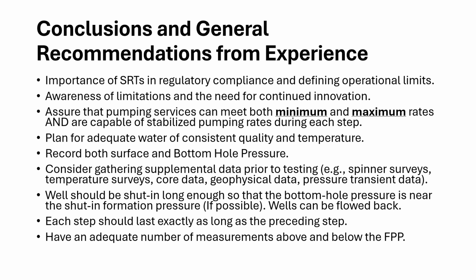So I would recommend that pumping services, when you're preparing for a test, be able to pump at the minimum and the maximum rates in your procedure. Oftentimes, the minimum rate is going to be a quarter barrel per minute or a half a barrel per minute, and that can be hard.